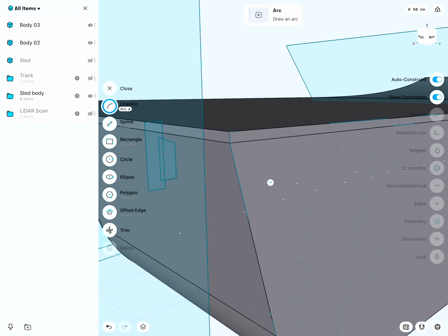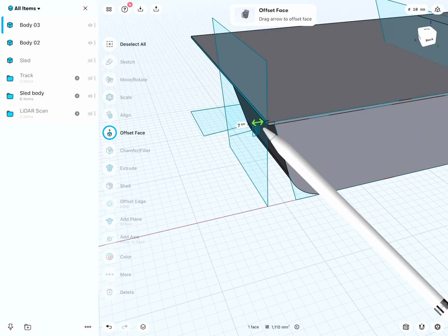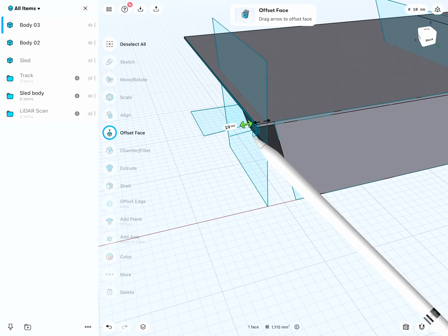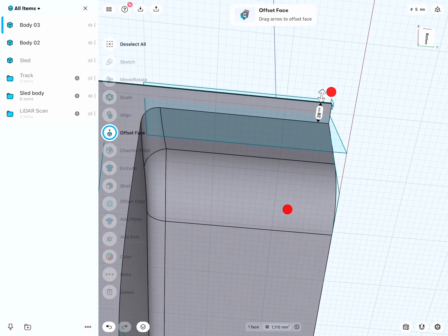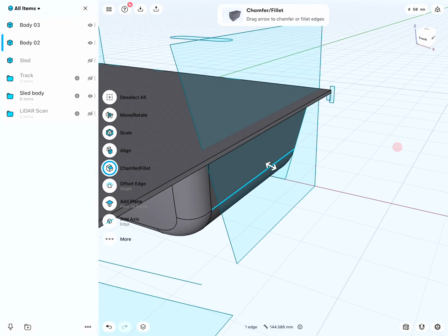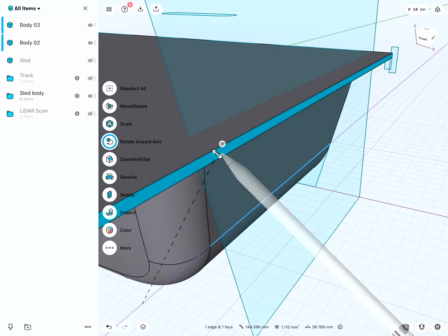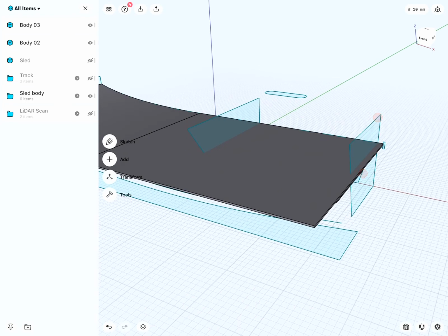I will explain in a moment how I made that sketch too. This here we will extrude by 2 centimeters, so 20 millimeters. That was very easy. This line is also linear, so this face I only needed to extend by 2 centimeters.